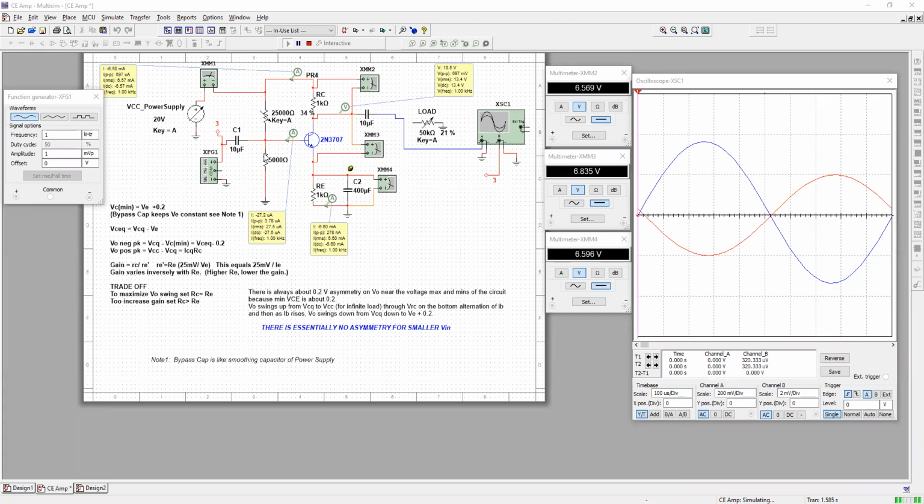So now we want to be careful not to raise this resistor too high. If it starts to get close to the effective resistance of this stage that it's feeding, you're going to impact the voltage division. You're going to create unwanted change, unwanted dampening of your base current. All right, so this is all about trade-offs. Now we'll move into this part of the circuit.